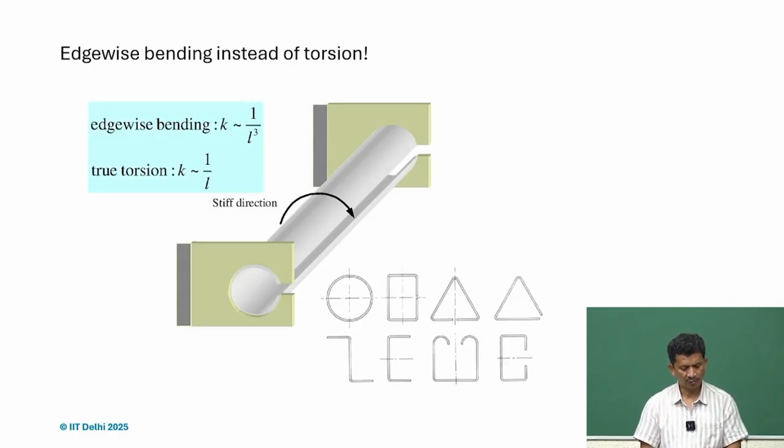So what we also have to understand is that even if it's an open profile, and suppose we seize the relative motion either by locking along the seam or locking the movement at the ends, many times we can achieve the stiffness of the closed sections. And many times we want these open sections because of the manufacturing, the ease of production of these kinds of sheets.